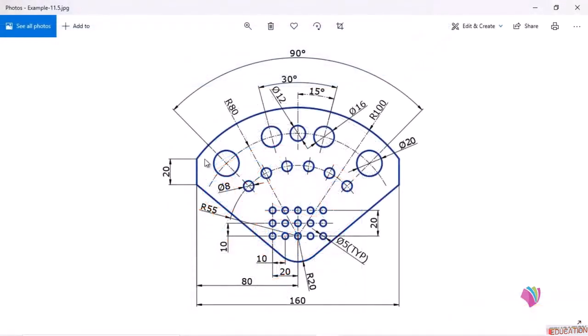Now at first we are going to generate this outer boundary as I have told you. So let us see the dimensions associated with it. This outer boundary is a collection of an arc and some lines, another arc and some lines here. Now, the boundary also we are going to create step by step. First, we are going to take a circle here and constrain it. Then another, bigger circle here and constrain it. Then we are going to create these lines. Let us start and you can see what I am talking about.